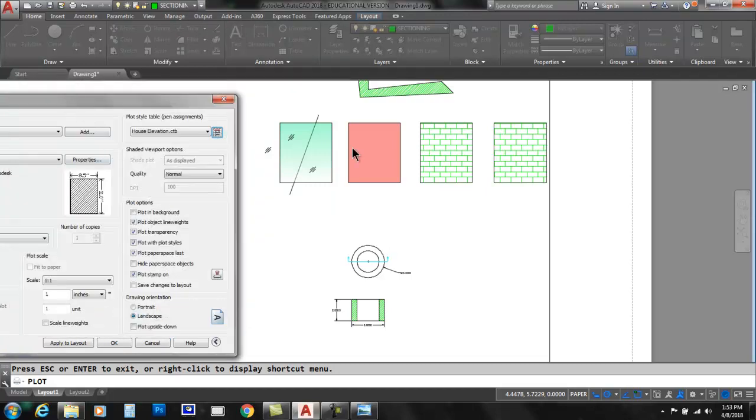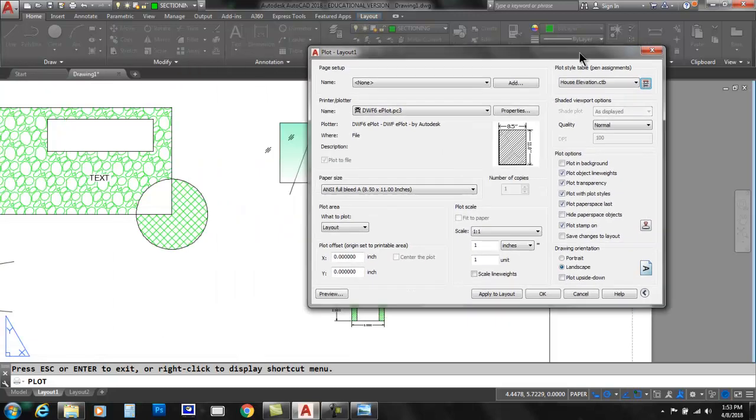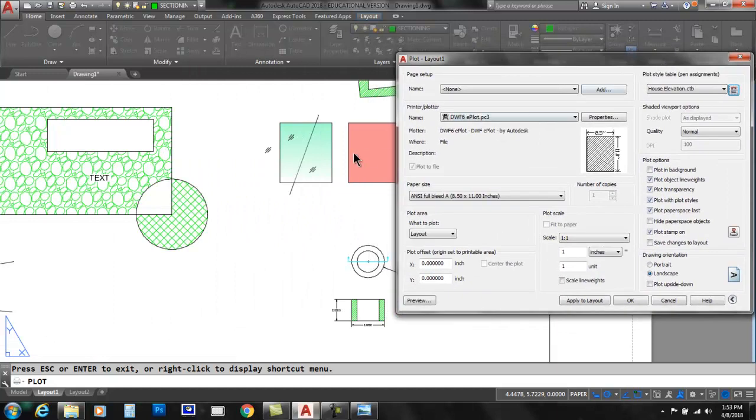Now, this drawing, we're just kind of making it up as we go along, but this is not going to be good because these glass lines are going to be thick and probably bleed into one another. So that's the importance of making layers. I should create a layer for glass with a different color, maybe a dark gray or something, and put these lines in there so that this is not affected by what's about to happen. So let's do a preview.